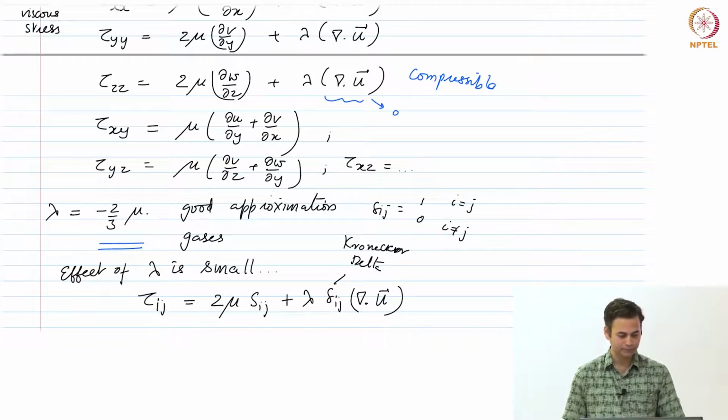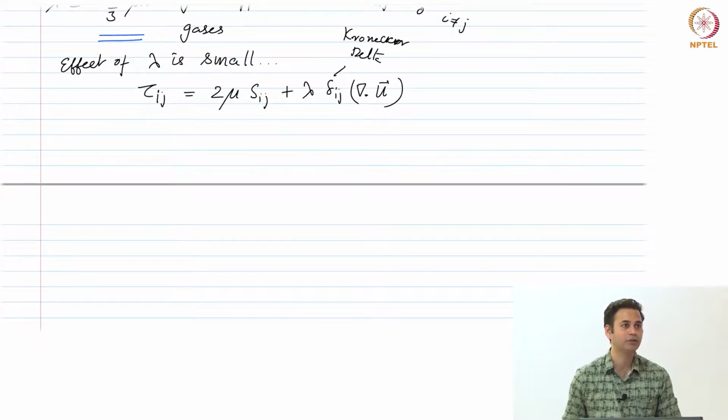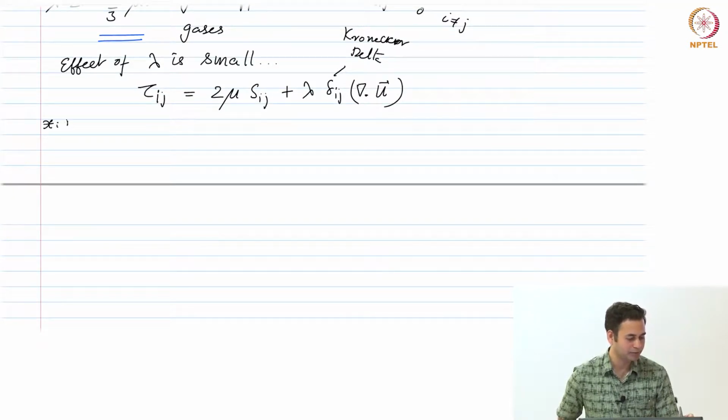Now we have brought in Newton's law of viscosity and related the shear stresses to the strain rates. Now, what do we have to do? We have to plug these shear stresses back into the momentum equations, and of course into the energy equation as well. So, we will plug these back into the momentum equation and see if we can get a nice equation that we can use to further integrate.